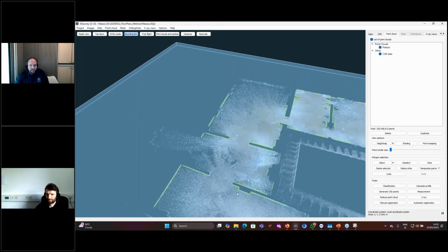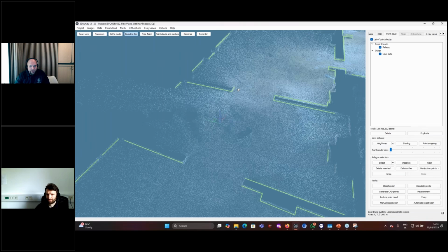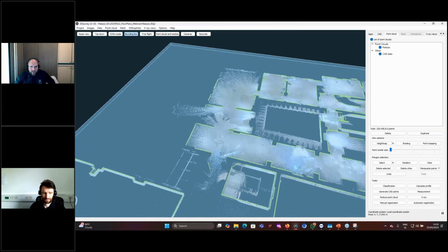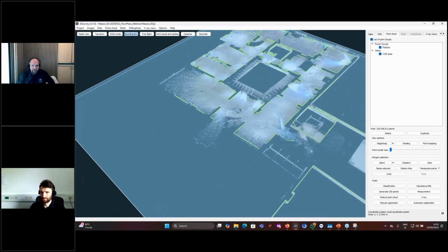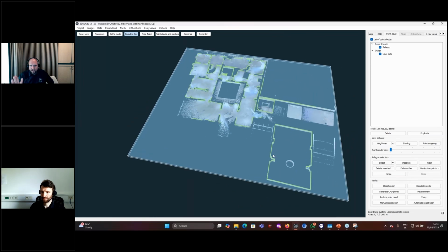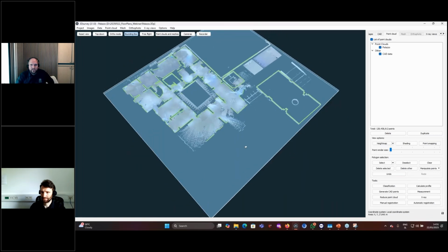So in this case, you would just have to go in here and draw these short edges, because for now our line detection algorithm has predefined parameters. One of those parameters is that the shortest edges that we detect are 30 pixels long. So if we have centimeters, that means up to 30 centimeters. So the walls will need to be 30 centimeters or thicker in order to get those side views. Otherwise, you have to draw them up manually.